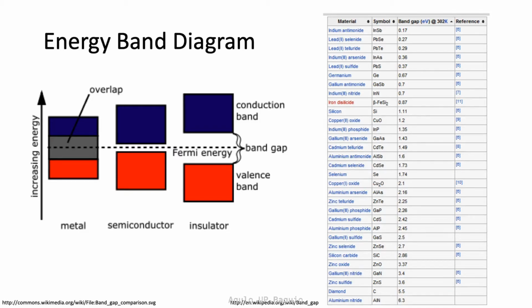The table lists a few semiconducting and insulating materials. There is no straightforward delineation between band gap energies of semiconductors and insulators. The definition presented here is very basic, and there's more to a semiconductor than just a low level of band gap energy. We are going to explore these properties of a semiconductor in the next few slides. For now, if you take a look at the table, you will notice that most materials with energy band gaps below 3 electron volts are semiconducting materials.